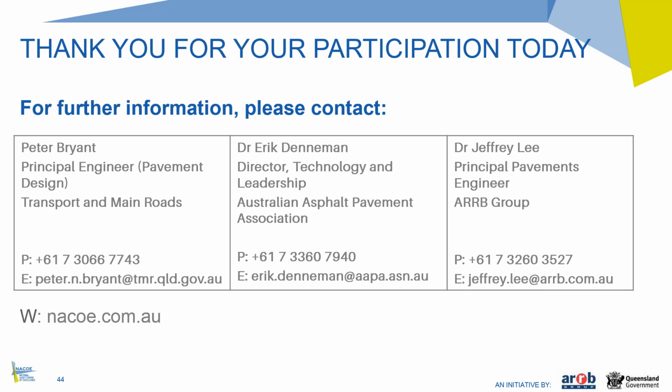For other construct-only type contracts, normally where the design's done separately and then that project goes out to tender, there's normally the opportunity for the contractor to submit an alternative tender. So in that case I would see the designs being done using the presumptive values. The contractor bidding for that work, if they so choose, could propose an alternative tender, or they could negotiate even after they've won the job to optimise the designs during the actual construction stage.